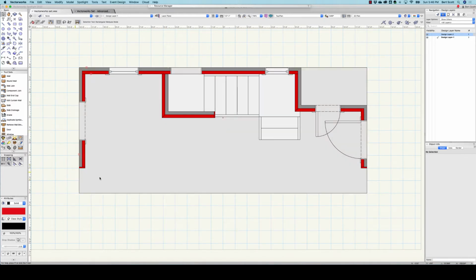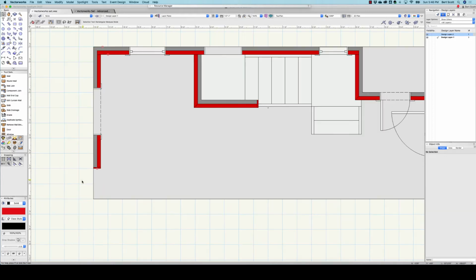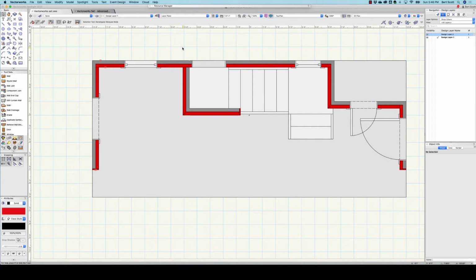And at the 3 points, the end of the wall here, the end of the wall here, and the end of the wall here, we would add 6-inch wide thickness pieces or reveals to make the walls appear to be 6 inches wide to the audience, when in fact they're really just standard flats. And they wouldn't be continuous. Each wall would be an individual construction. That being said, I don't want to get caught up in those details in this early model, so I just want to point that out, that we're drawing walls that are true architectural walls, but it would be very easy to change them to theater flats or theater walls when you did a final version of the model.